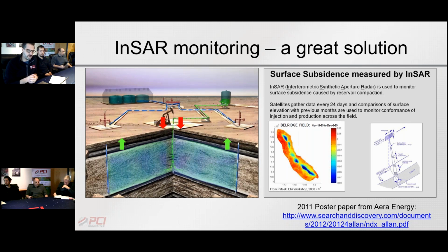So there's a lot of different techniques that have been used over the years to do ground surveying and measuring with prisms and a lot of different techniques. But kind of starting in the early 1990s with the advent of ERS-1, which was more reliable as a sensor collecting data than RadarSat-1, and now with Sentinel-1 and commercial sensors like TerraSAR and RadarSat-2, this is actually an operational way to monitor and inform decisions about how much oil to extract and how much steam to inject to manage that very delicate balance, to ensure that the equipment is not damaged.